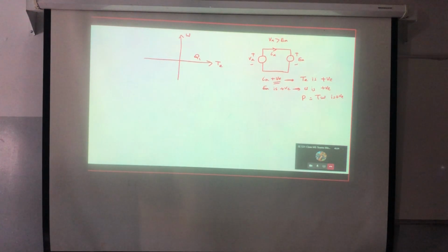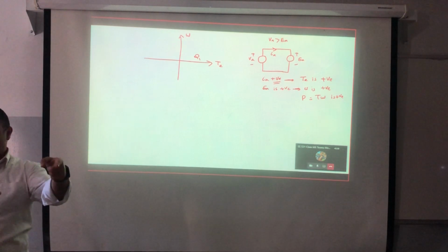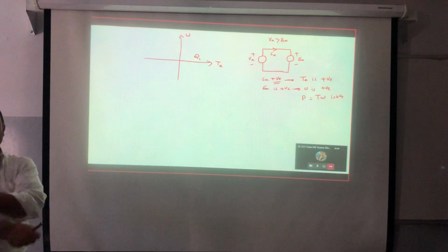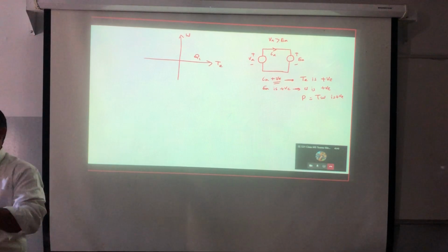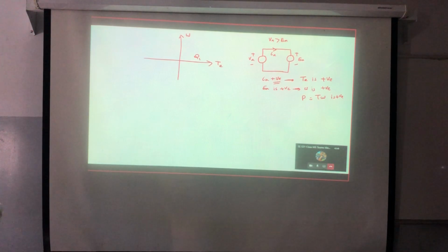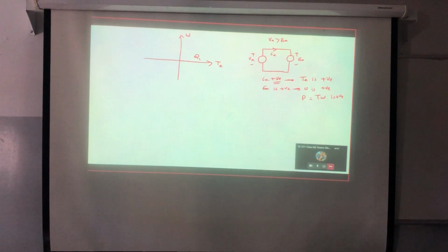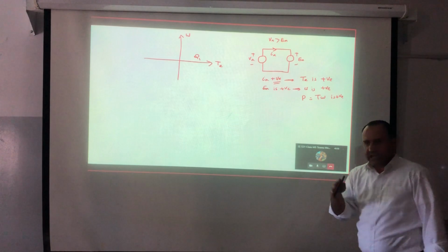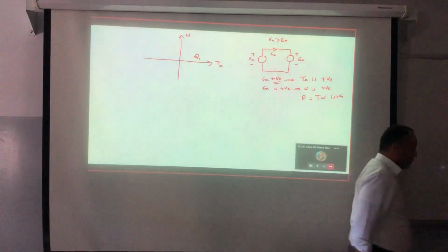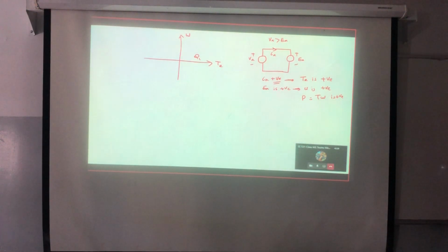If I need to do plugging for the series, I will disconnect the series field and connect it as a shunt, as separately excited, which means that I will reconfigure the machine. What about dynamic braking for the series connected machine? What will happen?